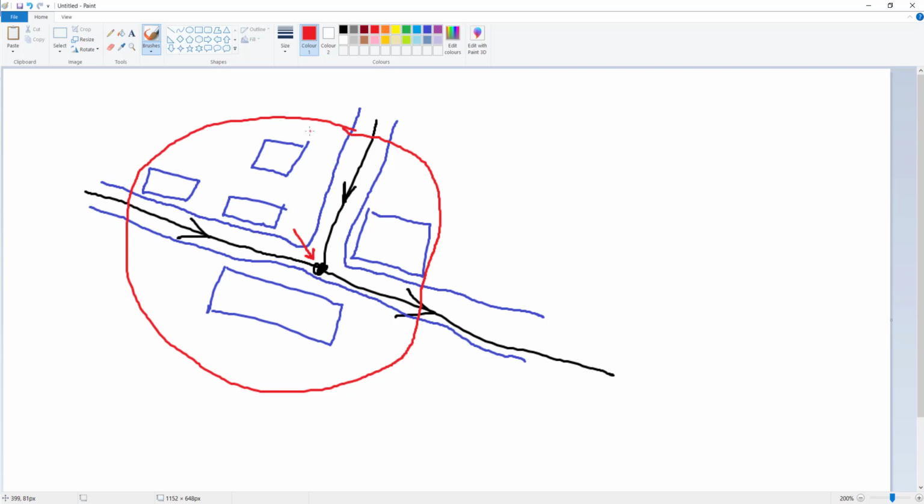What we also have to do, either by using GIS or estimating, is work out the PIMP value, percentage impermeable. In other words, the amount of catchment that has been tarmacked or concreted over, because crucially, InfoDrainage only accounts for runoff from those impermeable areas. So we're only going to get runoff from the roads and the roofs and nothing from all the other areas, the back gardens, the grass verges, everything like that.